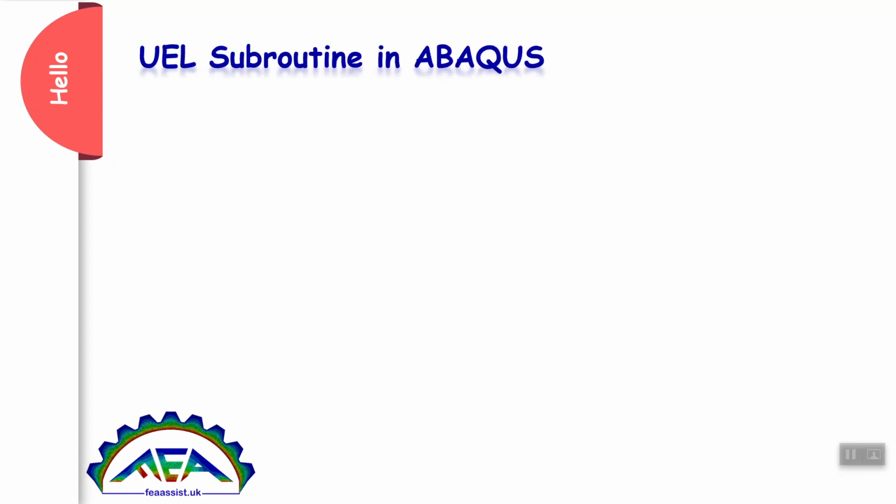Hello, you want to learn UEL subroutine in Abaqus easily and quickly. UEL is a subroutine to define a new element in Abaqus. Consider you have a one-dimensional element with points A and B. For example, temperature in this element is interpolating between the temperature of point A and temperature of point B. So an interpolation function computes and defines the temperature in any point in this element.